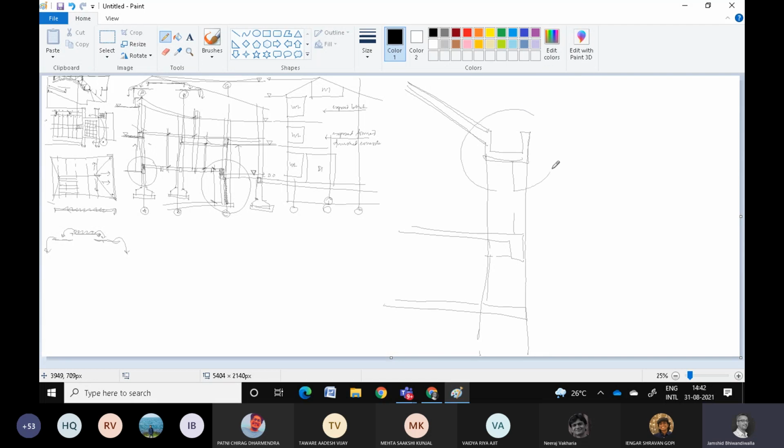These kinds of gutters work best when you have slabs that end with a beam, which is called a gutter beam. However, with metal sheeting, when we try to give gutters, it tends not to work well.